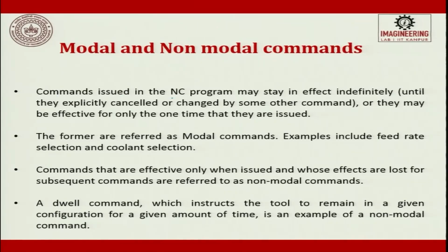Commands used in an NC program may stay in effect indefinitely until they are explicitly cancelled or changed by some other command, or they may be effective for only the one time that they are issued.